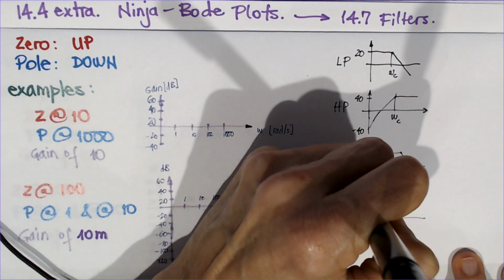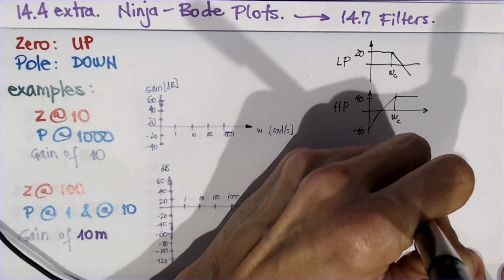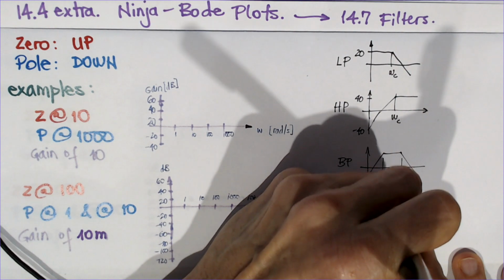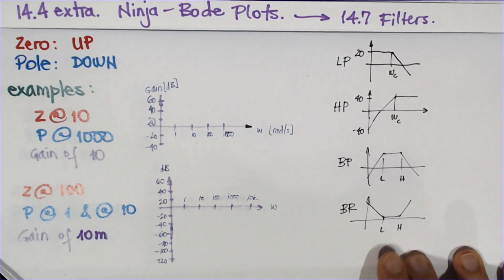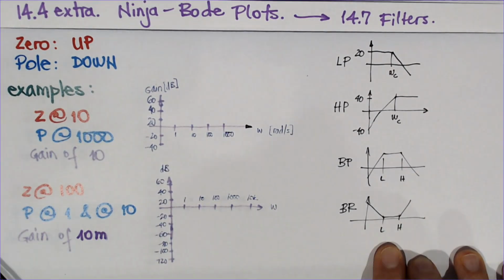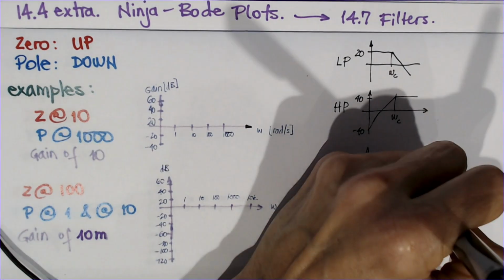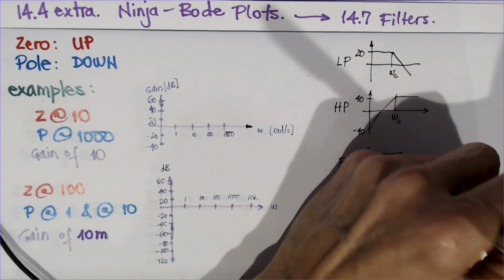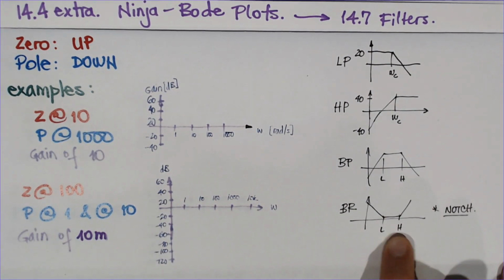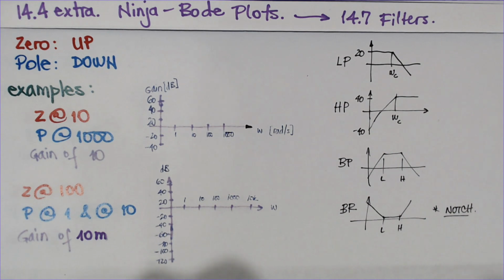which is you have high gains for everything here, but between the low and high, you have very low gain. This is typical. The most used one that you may be asked to design is a notch filter, which takes out, for example, 60 hertz, or in Europe it's 50 hertz. So as I was designing systems in Germany, we made notch filters for 50 hertz.